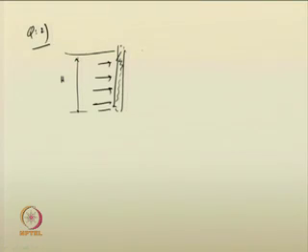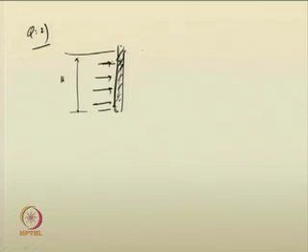The second question we asked is, in the vertical sluice gate, why you require to design for pressure. Say if a vertical sluice gate is made like this, on the left side water is there, with certain pressure already. Now, as a vertical plane has been incorporated, due to the pressure, a force acts perpendicular to this particular plane.